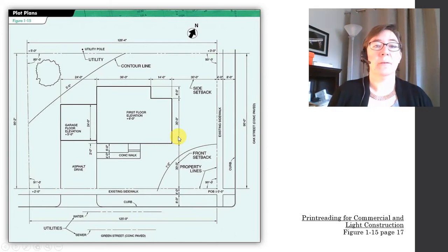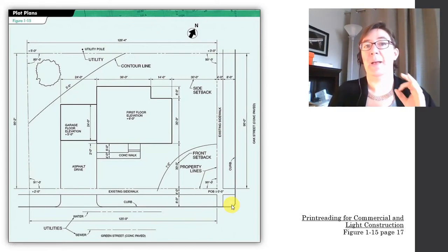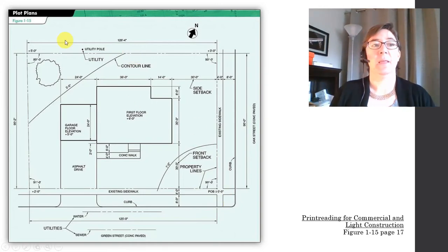If you step down from that profile line weight to maybe a heavy line weight, we can see contour line, we can see this bush, and we can see the driveway and sidewalk lines. A lighter line weight, so perhaps a medium line weight, is these dimension lines and leader lines.